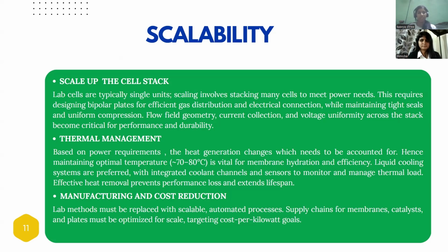First point is the bipolar plates. For efficient gas distribution and electrical connectivity, we will have to ensure that these plates, as mentioned during the components, are given proper consideration. Followed by that, the flow field geometry is also going to play another important role. It is going to ensure the even distribution of reactants and maintain uniform voltage across the stack.